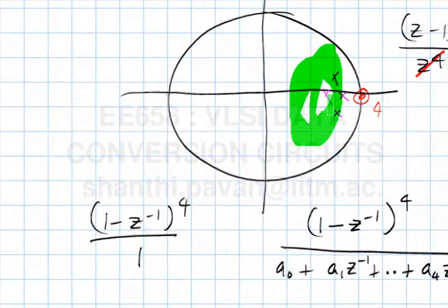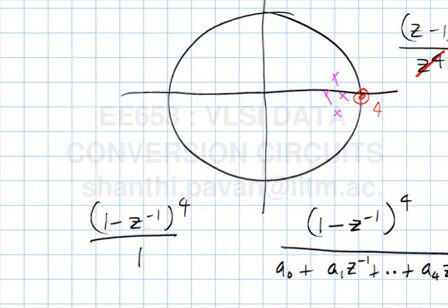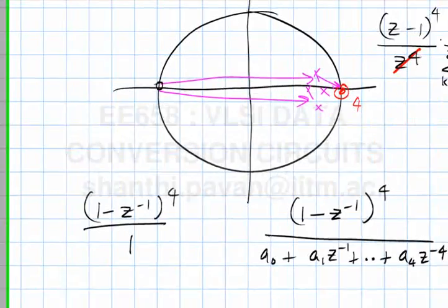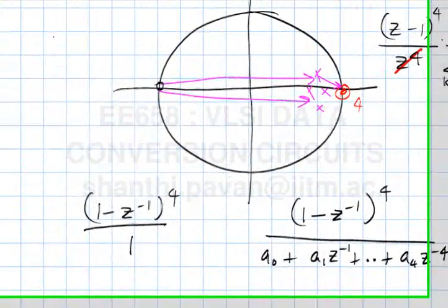somewhere around here. And poles here basically means that the gain at omega equal to pi, which is z equal to minus 1, is inversely proportional to these vectors. So you can see that due to the placement of these poles, the gain at z equal to 1 is definitely smaller than the gain at z equal to 0. And you want these extra poles to form a low pass type function because you want to filter off the high frequency part of the quantization noise, which means that the gain at 0 must be larger than, you want something like this.